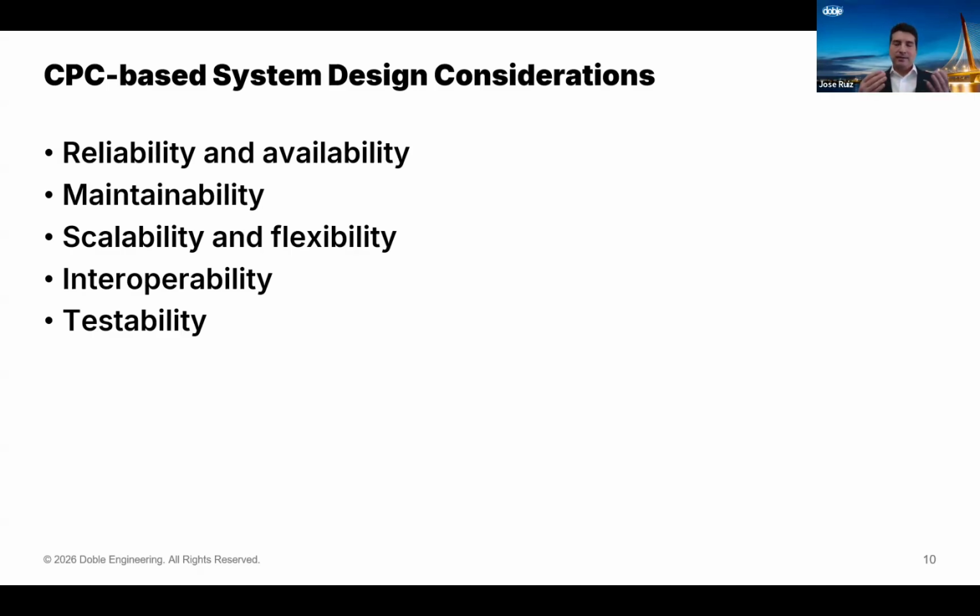By the way, I just want to emphasize again, the GOOSE message in the IEC 61850 is the digitalization of the binary inputs and binary outputs in the microprocessor-based relay. So today, if I'm testing a microprocessor-based relay and I want to test a specific element, I can use a spare contact to make sure that's the only element operating, nothing else getting in the way when I verify the operation. That's an element testing approach. So something similar can be done here if we take testing into consideration when we're designing the CPC system.